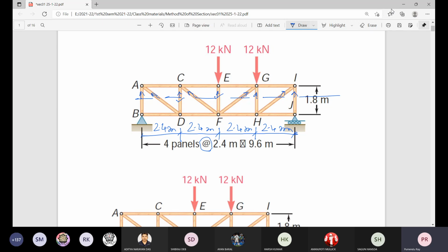So when you are asked to find out the force in this member and in this member, you select section 1.1, and you can select this also. Two, because in that one this is already known from section 1.1, and here it is left only with this unknown force and this unknown force, and you can find it.